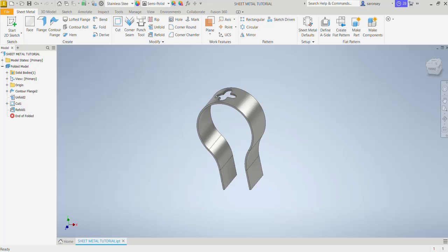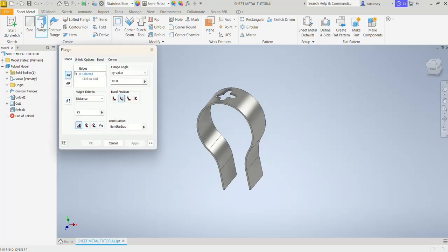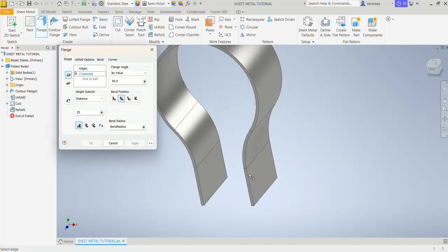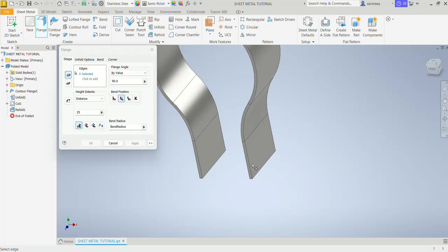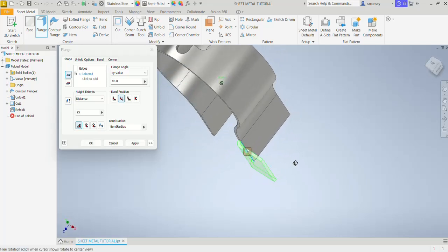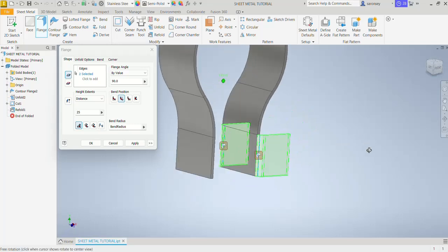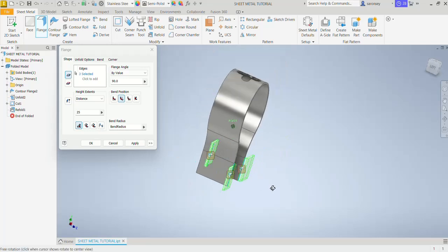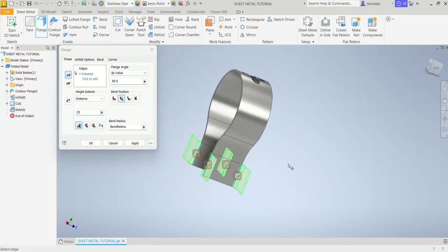Looks good. We'll go ahead and create some flaps or flange on these parts, this face and then that face. So we'll select our flange command up here. Flange, we click. And then first of all, let's choose those lines we would want to apply the flanges to. So this one, choose the outer line. Straight away we see a profile. That is what we like. And then that, let's select all 4 lines here, and then finally there.